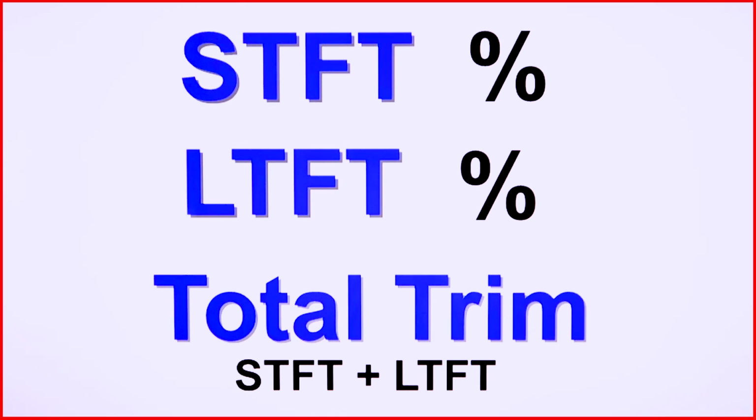Now, I know one of the questions that came in already, we'll quickly address that, is what's a good value of fuel trims? It's always been kind of a good value to say plus or minus 10%. No vehicle is going to be perfect, and so there's always going to be some type of correction going on there. So based on the manufacturer, you might observe different trends. I've seen some GMs that like to live in that 8% range, or so over time you're going to learn your own values here.